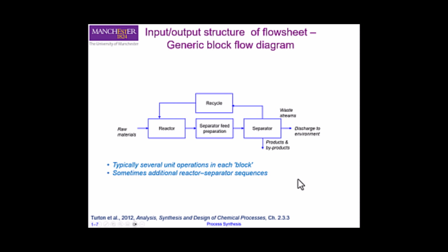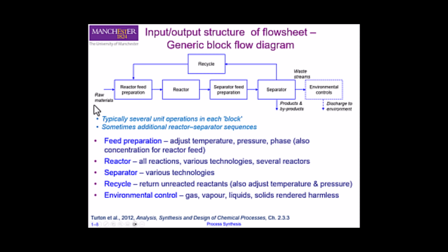But depending on your system, you might want to add more details. For example, you might want to add a feed preparation step because you might have to raise the temperature, pressure, or change the phase of your reactants before you feed into the reactor. The reactor itself can be a series of reactors or can be different technologies. For example, similarly, there are various technologies available for separation: distillation, membranes, absorption.